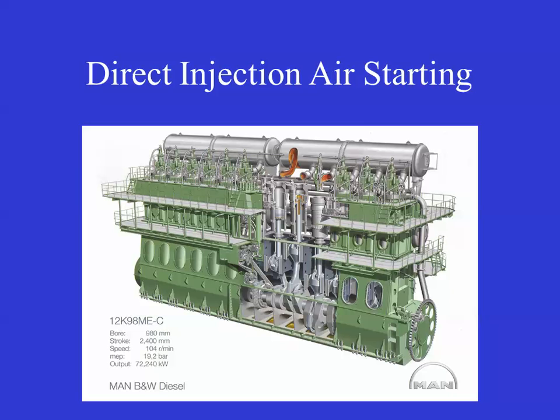Let's go ahead and talk about direct injection air starting. Large engines typically are air start. Again, respect the air start bottles. They are a bomb sitting there. The whole idea of having a pneumatic starting system is you are storing huge amounts of energy in those bottles.